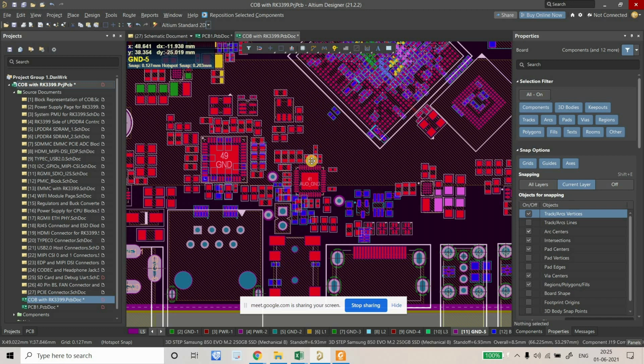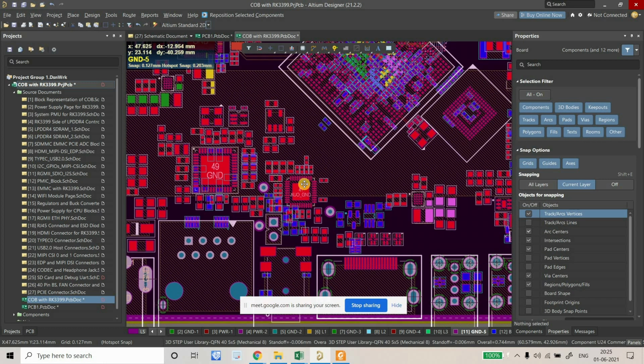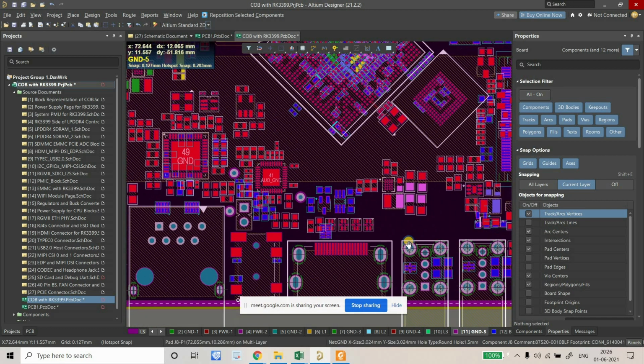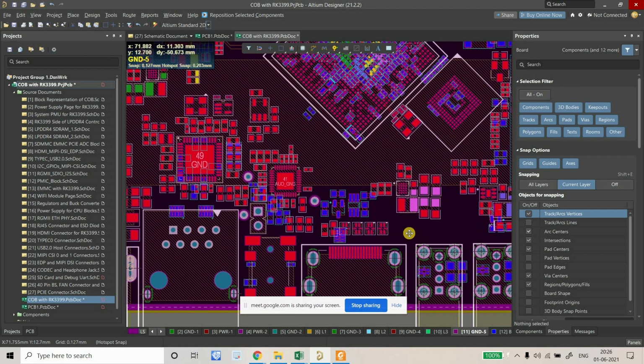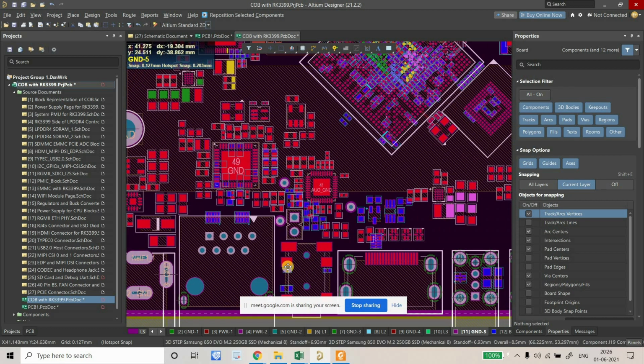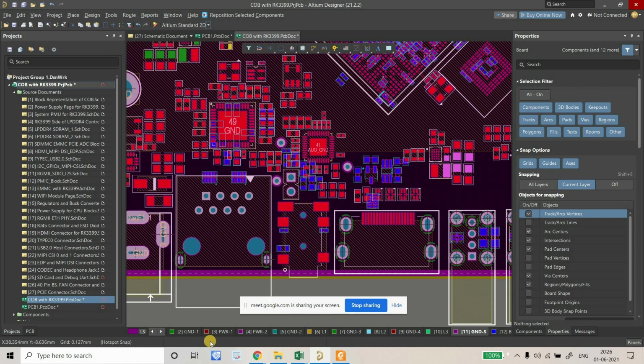You're getting it? When you are using the via, make sure, there are types of vias on which you can remove the pad if you don't want to connect all the ground planes together. But at the end everything will be connected. So this you can do. We have like 4 or 5 ground planes. You have to place a fill, or you can say a thick line, on that.